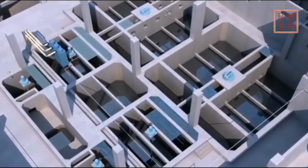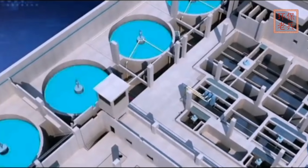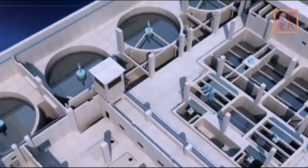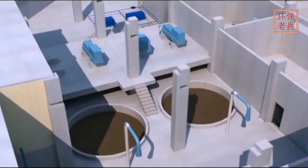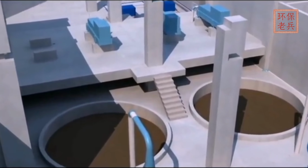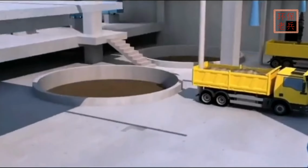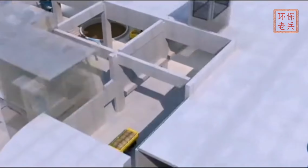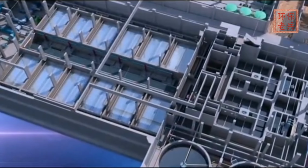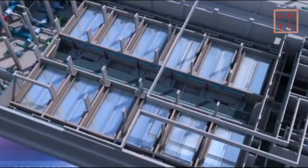In this tank, through mixing and chemical dosing, suspended solids form sludge that settles to the bottom. This sludge is pumped by circulation pumps to the sludge thickening tank, where it joins the sludge from the secondary clarifier. Together, they are conveyed via sludge pipelines to a sludge holding tank and then sent to the dewatering room. After dewatering, the sludge forms cakes, which are transported by piston pumps to sludge trucks and hauled away.